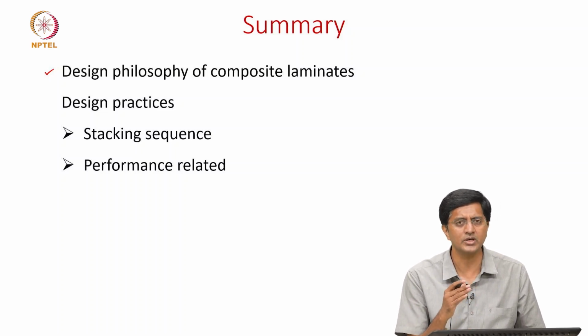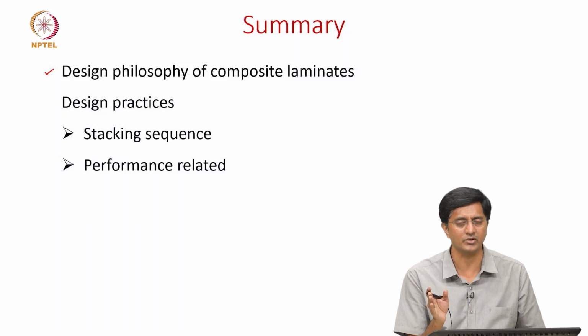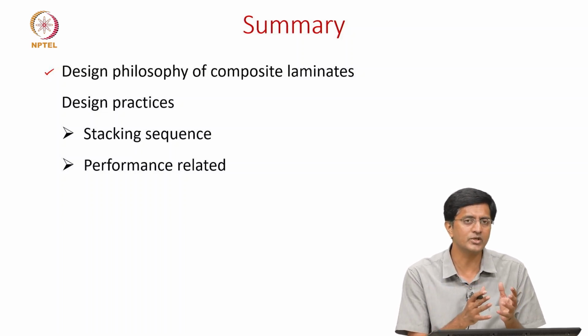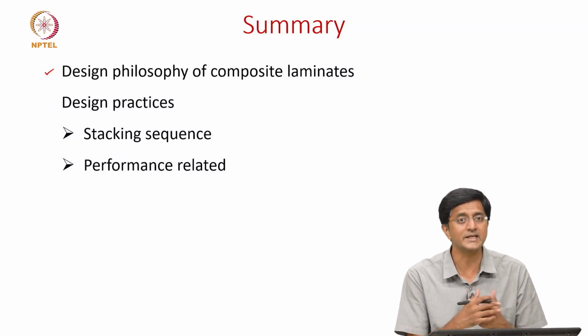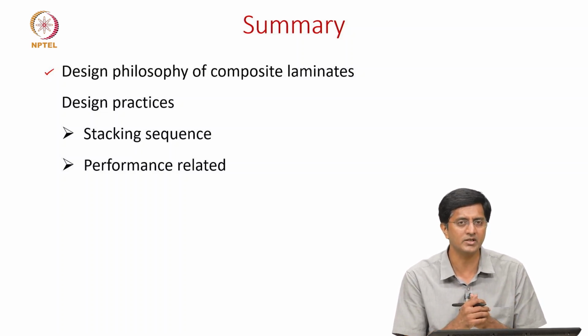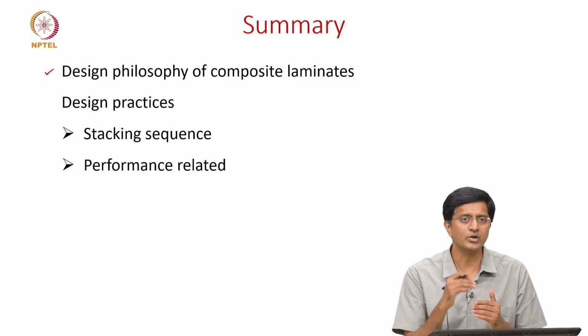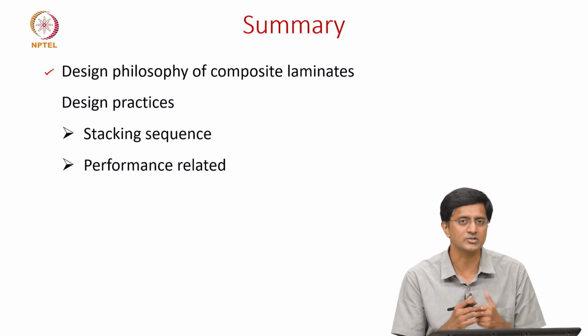We also looked into the philosophy: should we go with the first ply failure or the ultimate failure load? We said first ply failure is a very conservative design, which is okay if there is less confidence in the design of these materials. But if there is more confidence or more data available and a lot of experience using the particular composite material, then one can move beyond the first ply failure and take advantage of the extra loads the laminate can sustain beyond it.